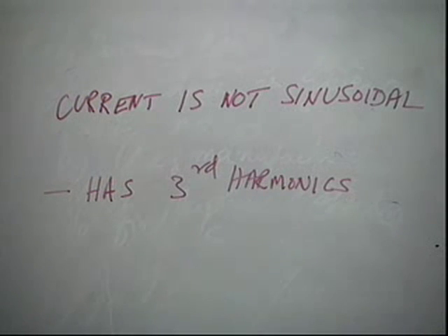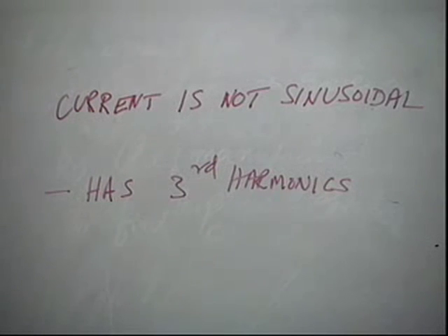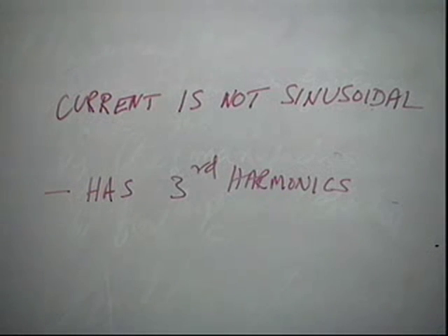Yes. So which current is this? Is this the electric current that is applied or the magnetic current that is flowing through the circuit? Both are same. After all, there are no two currents. I have only one winding. It is drawing a current. That current is going to magnetize the core, and because that magnetization is decided by the voltage applied, the current drawn from the supply will be non-sinusoidal.